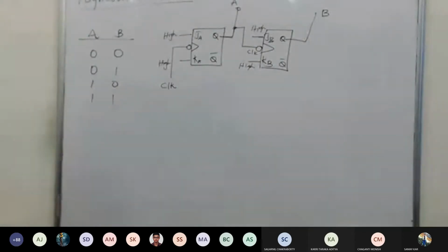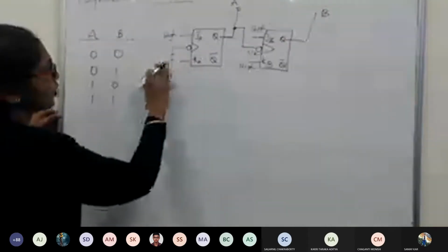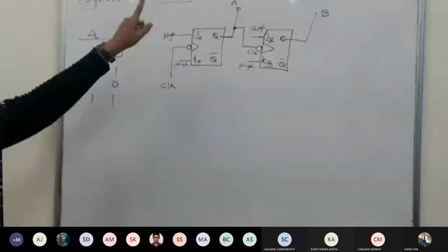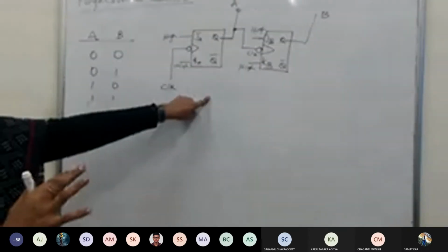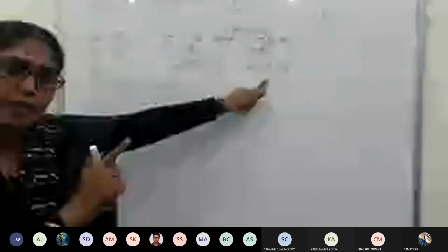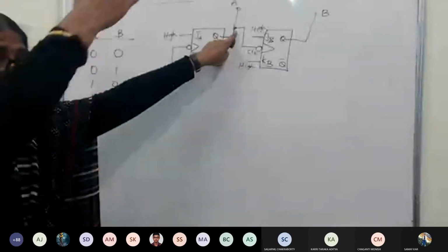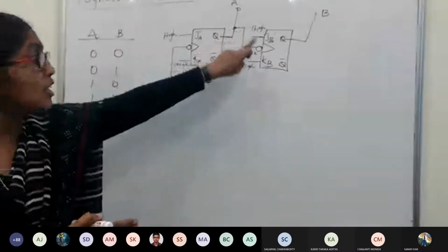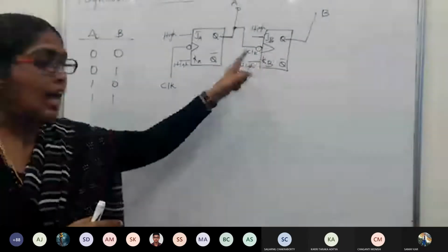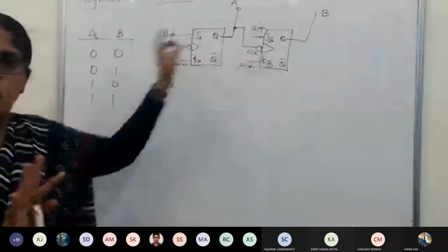Now what is the analysis here? First thing is, when the inputs are already provided, this is high, this is for K. So what exactly does it do? This one will react. The second flip-flop, which is called the B flip-flop, has to wait. Why? Because this has to enter the 1 to 0 zone. Then only this will react because its clock, which gives the permission to work, is tied to this one. So unless A goes through this, it won't.